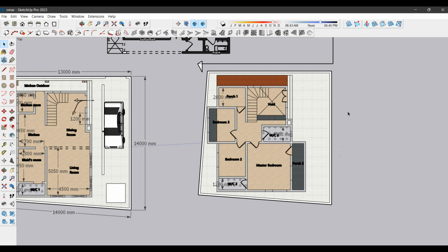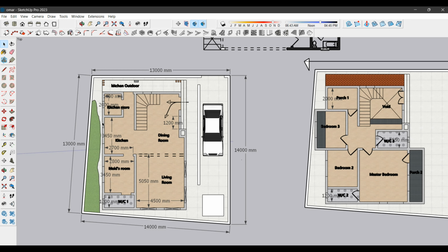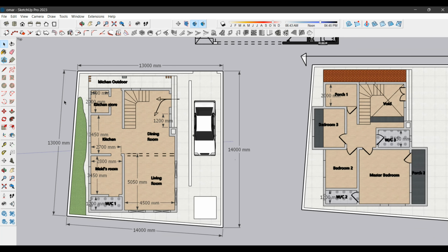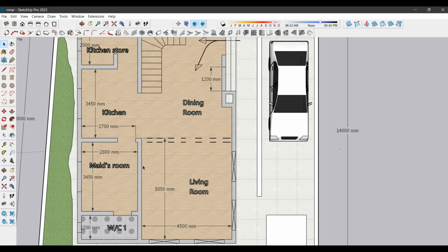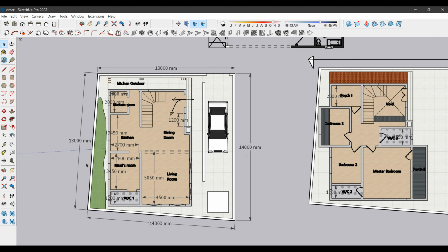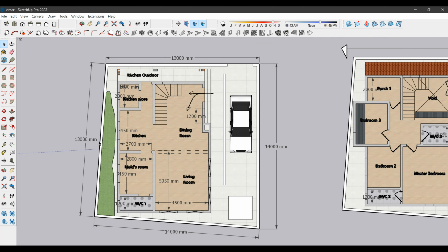Also, there's the issue of electrical works, where these guys sometimes tend to break into the walls. Structurally, for load-bearing walls, that is not recommended. There are even certain buildings where plumbers and electricians break into the columns or the beams themselves. That is not structurally safe.